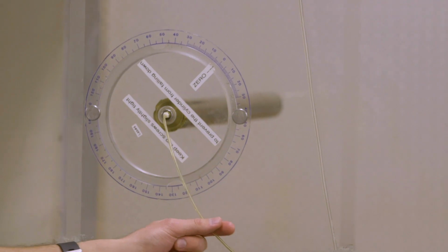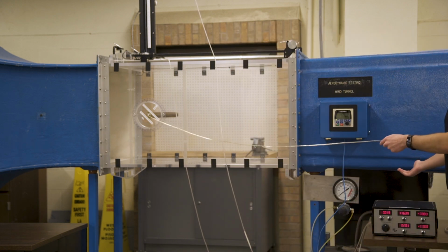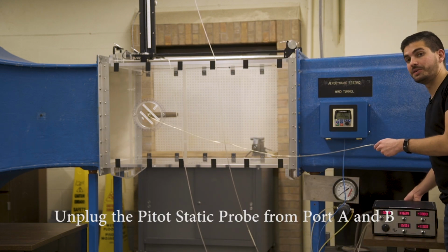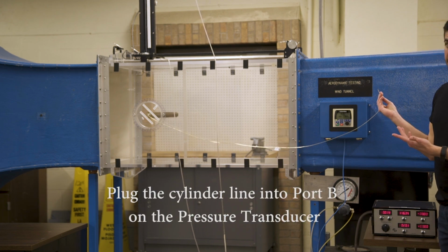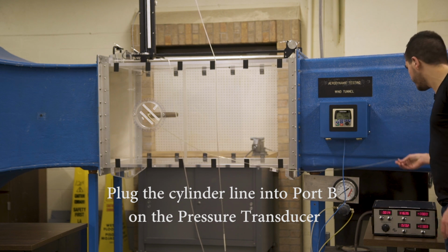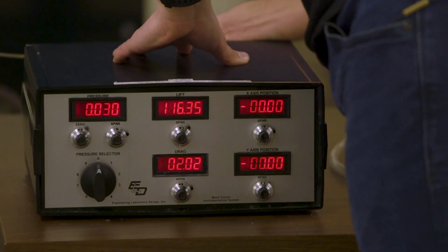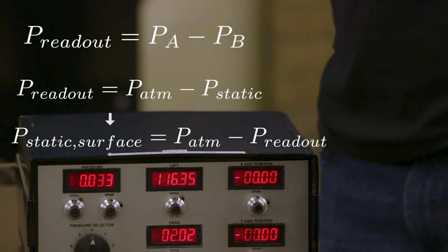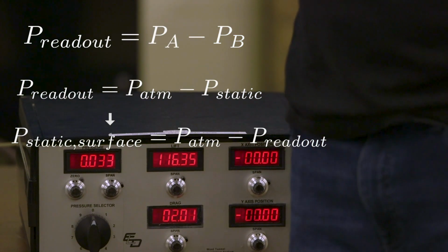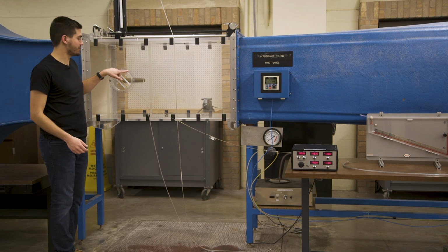So we'll follow this line coming from the cylinder and follow it all the way to the pressure transducer. Right now we've still got our pitot-static probe plugged in, so I'll unplug both of those. Then you should plug this line, which comes from the cylinder, into port B of the pressure transducer. Now it's plugged in, and what we're reading is the static pressure along the surface of the cylinder. And we can see that there's a scale here that shows us what the angle of the pressure tap is.